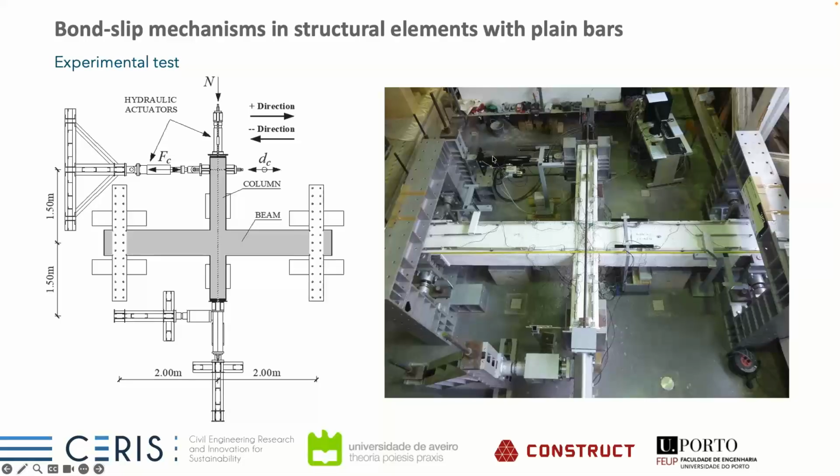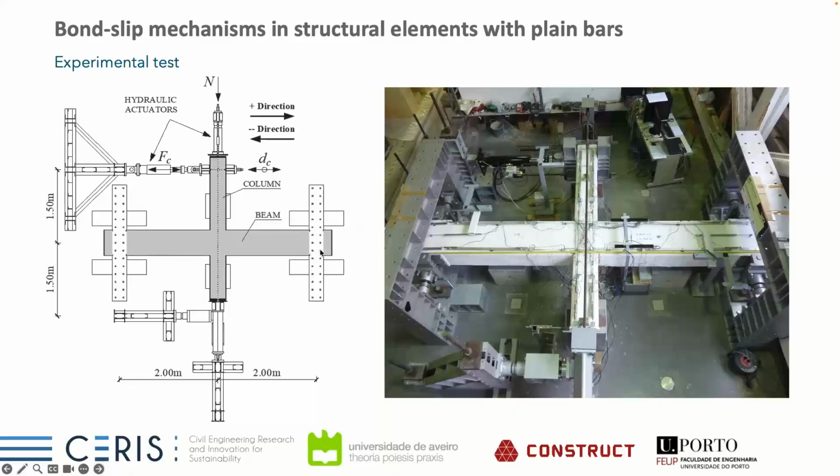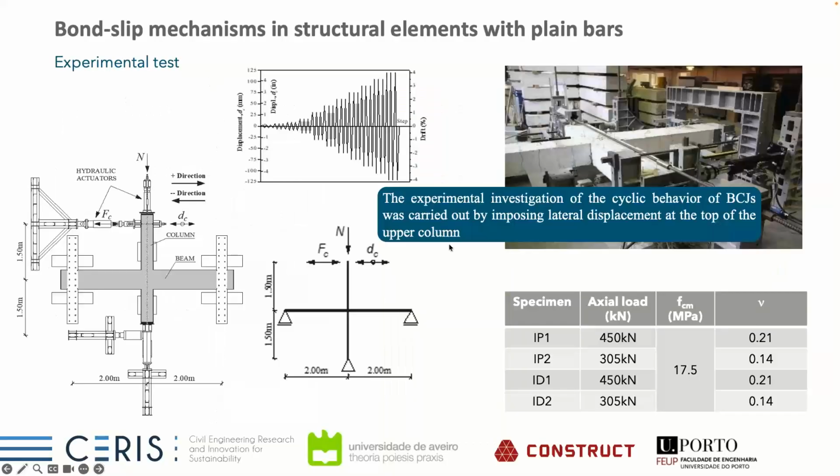And then the horizontal deformation is applied here in the column. So we have here the half of the column, so the inflection point of the columns. Here we have an additional length. The reinforced column is shorter, but we have an additional length to make sure that we have the right inflection point. And then the beam is supported here in these elements to make a simple support.